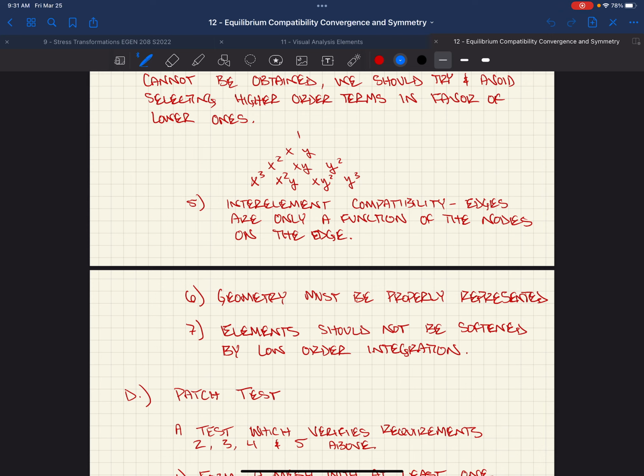Well, doing 10,000 points is a pain in the software program. It takes a lot of time. We want to minimize computation, and if it's doing that for every load that you put in VA on a plate element, and it's doing a definite integral for our equivalent energy forces, every time it does a definite integral it's going to use Gauss quadrature to do the numerical integration. If we did 10,000 points, every one of those plate elements would have to do that. So in finite element analysis, we try and minimize this.